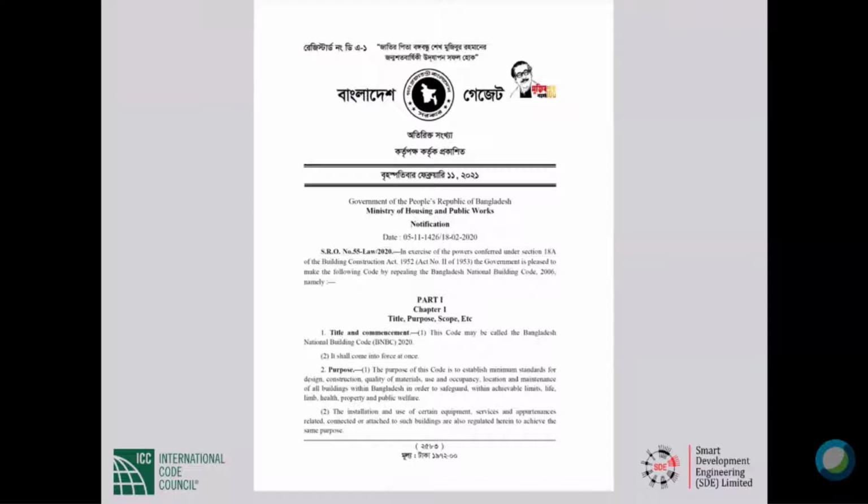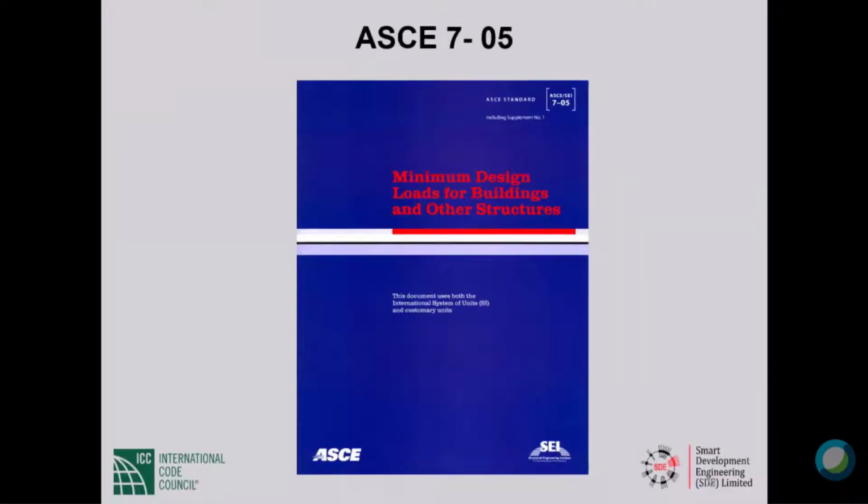Okay, the seismic design provisions that I will discuss with you are those from the 2020 edition of BNBC, which was gazetted, as you see, on February the 11th of 2021, very recently. It is important to point out that the code is dated 2020, but the seismic design provisions, like much else of the structural provisions, are based on ASCE 7-05.